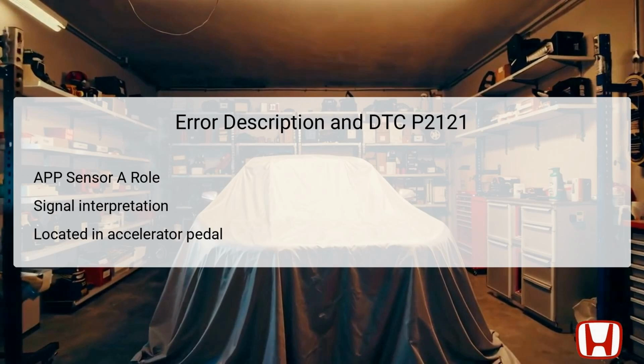This component is located in the accelerator pedal assembly, which makes it susceptible to wear, damage, or electrical issues. If the signal falls below 0.32 volts or exceeds 4.91 volts, it indicates a malfunction, prompting the DTC P2121 to register and requiring diagnostic attention.